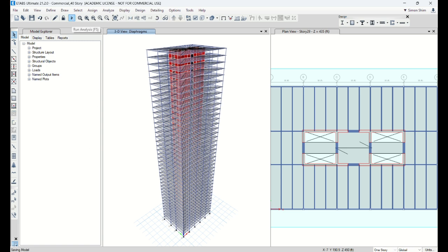Okay. So again, you need to define your wall, right? And define the material property, section property, and assign them. And you need to set up the wind load. You need to select and assign the rigid diaphragm. So you'll be able to do a test run.